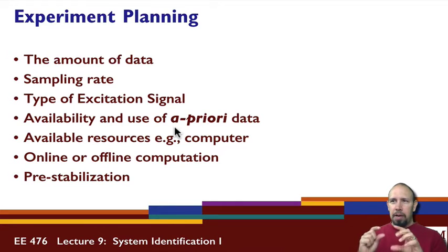That characteristic of applying a voltage, having the motor turn and then not going back after you release the voltage, corresponds to a particular characteristic of a system. That is, the system has a free integrator. The denominator of the system can be factored in the Laplace domain and have an S term by itself in the denominator. That fact is important in working with the motor. That's a priori data. We know that ahead of time, and so we can incorporate that data into our model when we work with the model to obtain the model parameters.